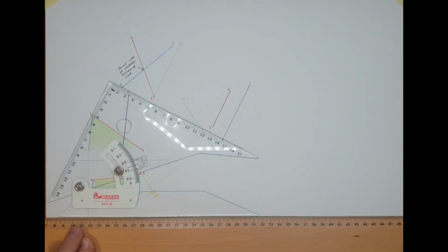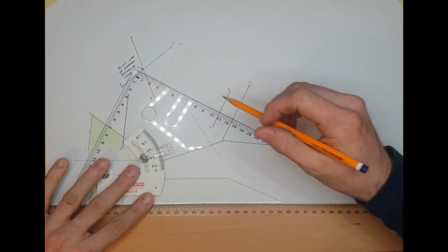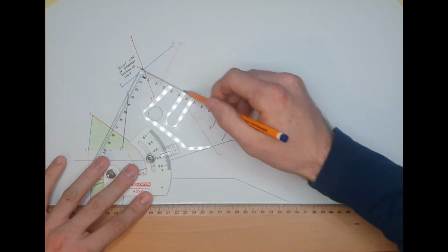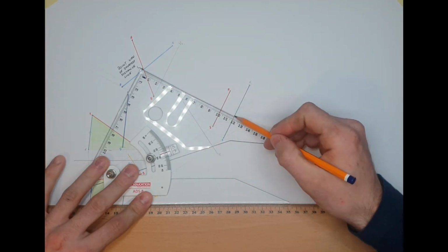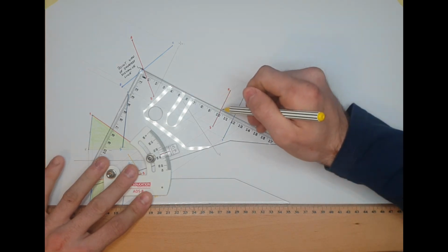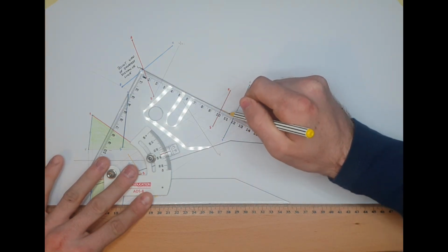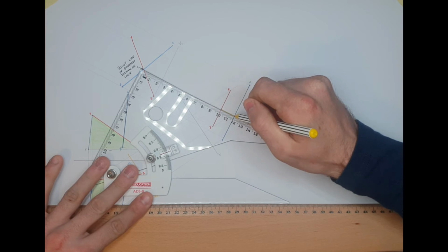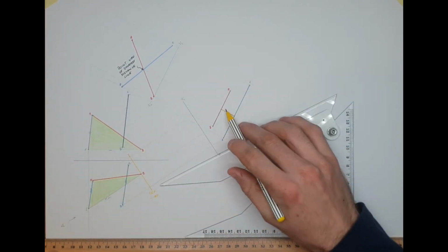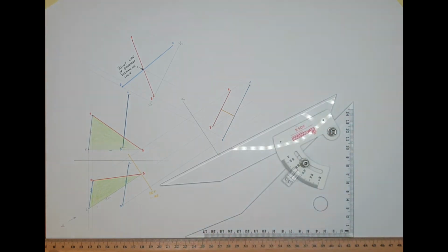Like we've always known, if you have a true length line in one view and you look along it, you get a point view in the next. So this is just that same rule worked backwards. If we have a point view line in this view, we have a true length here. What colour had I used? Actually, that's it. I didn't think I'd need the yellow, and that's why I used it for a reference, but I had used yellow as my reference colour for the shortest distance line, and there it is. That is a true length of the shortest distance line.